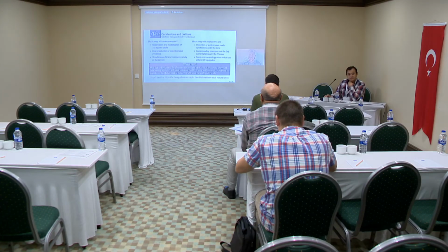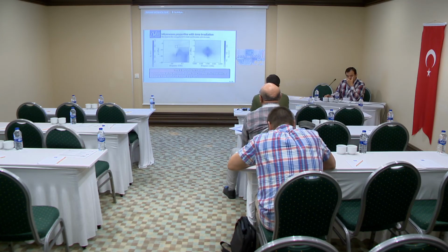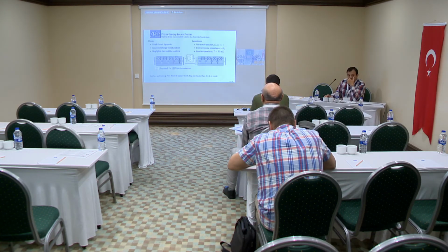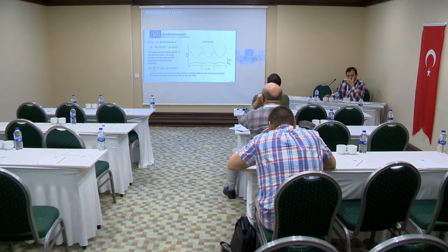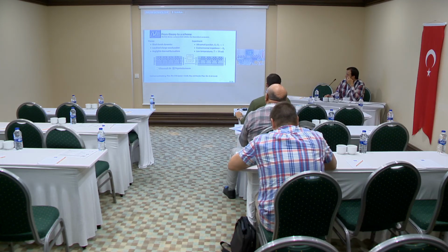With pleasure. So in order to keep your system in the lowest band, it's not sufficient to control a J over C ratio, but you have to have some portion of dissipation. Otherwise, sooner or later, your system will go to higher bands due to Zener tunneling. So the question is, what is the dominating mechanism of dissipation in your experiments? Is it due to plasmons in these transmission lines which you have on both sides of your junctions? I mean, these transmission lines formed by a series of junctions.